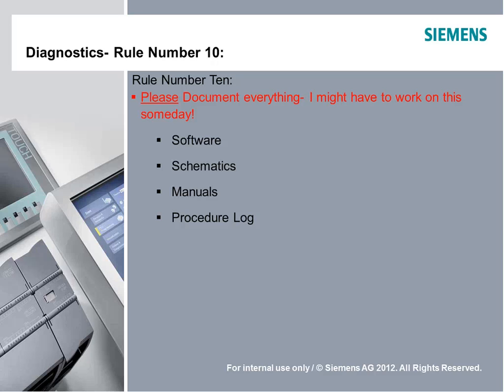Number 7 is use your tools. The diagnostic logs in the software will go a long way towards showing where faults are and help you diagnose things. Also, if you're designing a machine, think about the guy that's going to be maintaining it.